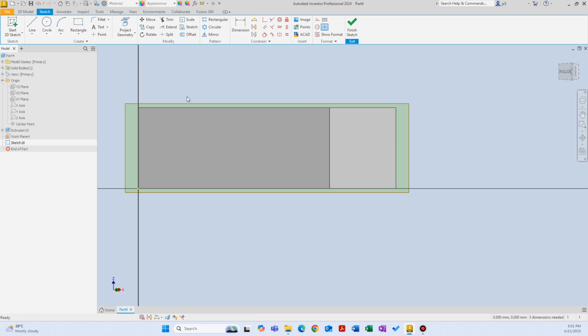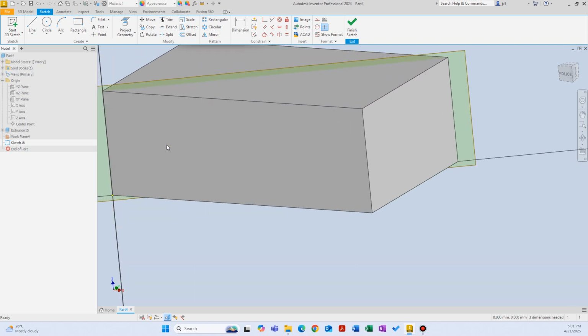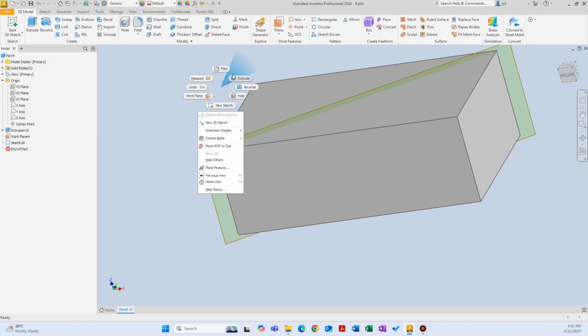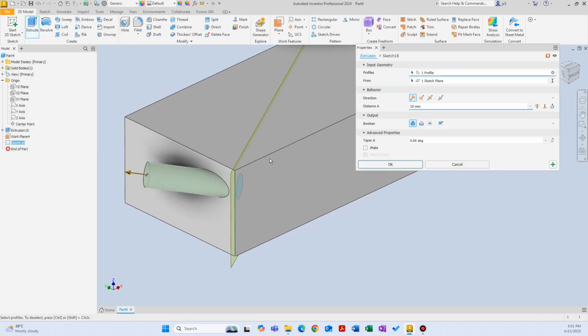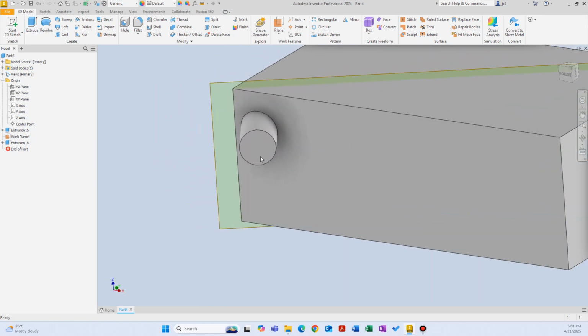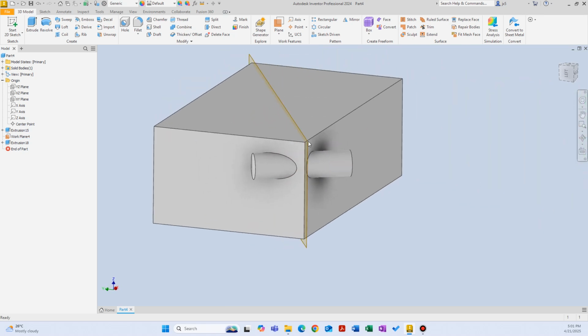Now you can't see that circle. It's just a little trick, by the way. In a sketch mode, if you hit F7, you can see the design you made. Right now, there's material in front of it, so that's why it's blocking us. I'm going to finish 2D sketch, and when you say extrude, you can see that piece there. Let's just say it's two-sided. Now we just created this weird looking shape on that plane that we created.